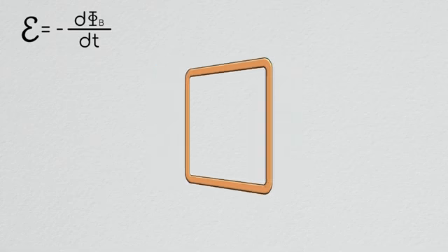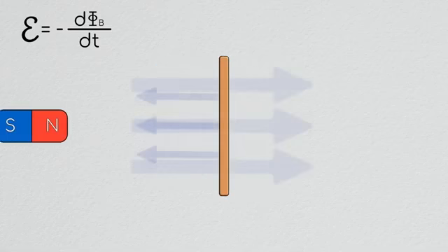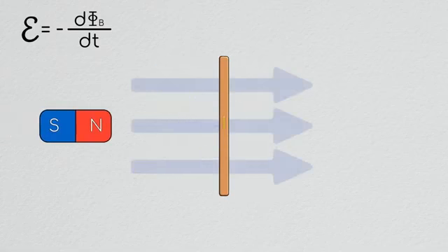For example, if the external field increased in strength, a field would be induced inside the wire which points opposite the direction of the external magnetic field. In a motor, this voltage is referred to as back electromotive force, or back EMF for short, and it's fundamentally important for understanding the dynamic properties of motors.